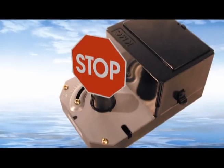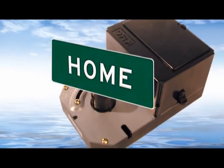Fail-safe actuators, on the other hand, return to a safe home position if the electrical power or pneumatic pressure applied to the actuator is lost. Such actuators are often used on crucial damper and valve applications that require protection from excessive temperatures, such as preventing coils from freezing or rooms from overheating.